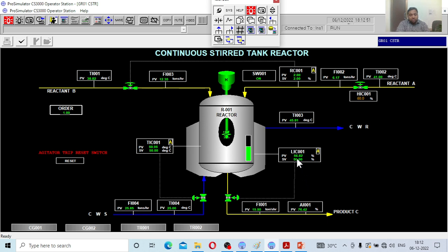Why? Because you see the level is getting down. The moment you put more reactants into the reactor, the level has been raised, the volume has been increased. If you increase the volume of the reactor, of course the conversion is going to rise at the initial time. But with time, the level indicator will try to increase the exit flow. Now this level starts to reduce. That means the level slowly comes to 50%, the set value. After some infinite time, the level is only 50%.